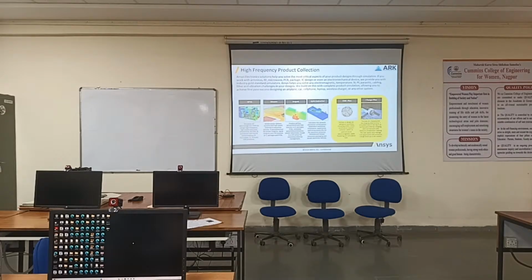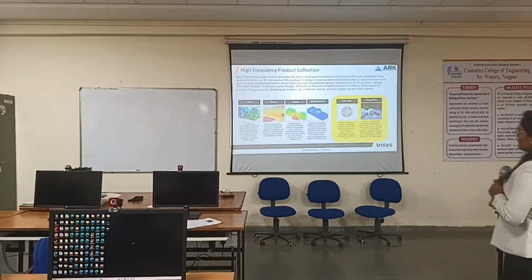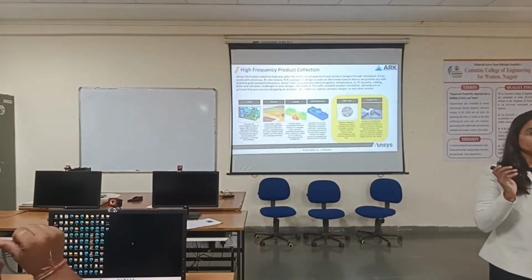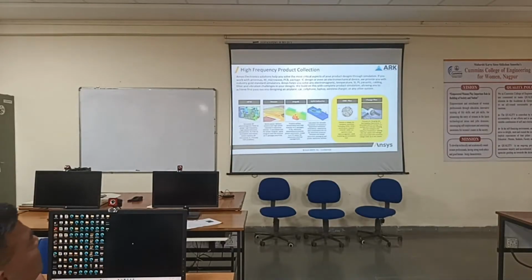The day before yesterday, Gandhi sir was talking about parasitic extractions, right? All the parasitic extractions on the PCB, whatever transmission lines we can see on the PCBs, their RLCG values we can identify using Q3D Extractor. Next one we have EMC Plus. All cable-related analysis we can do in EMC Plus, where crosstalk analysis or EMI analysis of the cable, if anyone wants to do in simulation, this is one of the important tools.